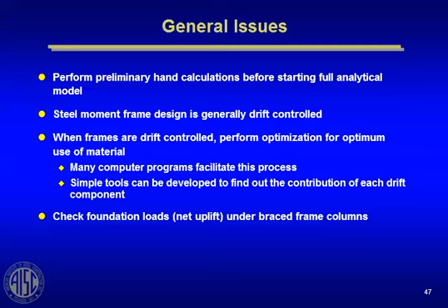So remember that. Braced frames are generally the frame of choice. The problem is architects don't like them because they take up space. So you've got to negotiate with them where you can have them. And you want to have them uniformly distributed over the plan. Another good system is to combine braced frames with moment frames, so you get this synergistic effect where the braced frame helps the moment frame as you go up and down the building. That's a good system to use.